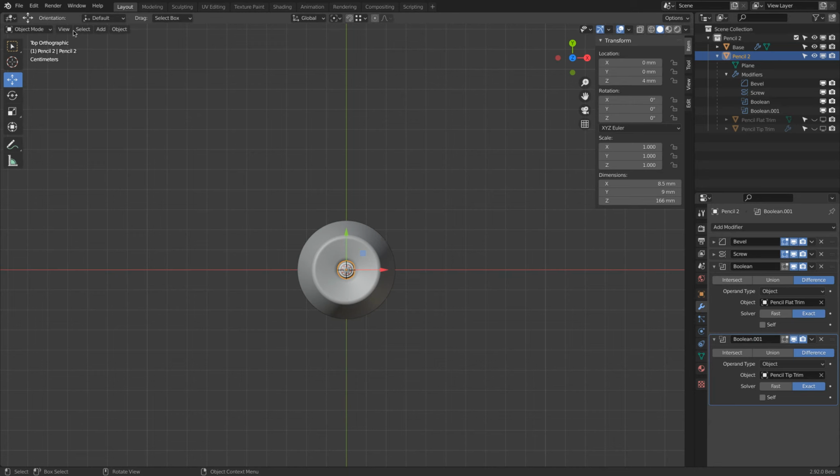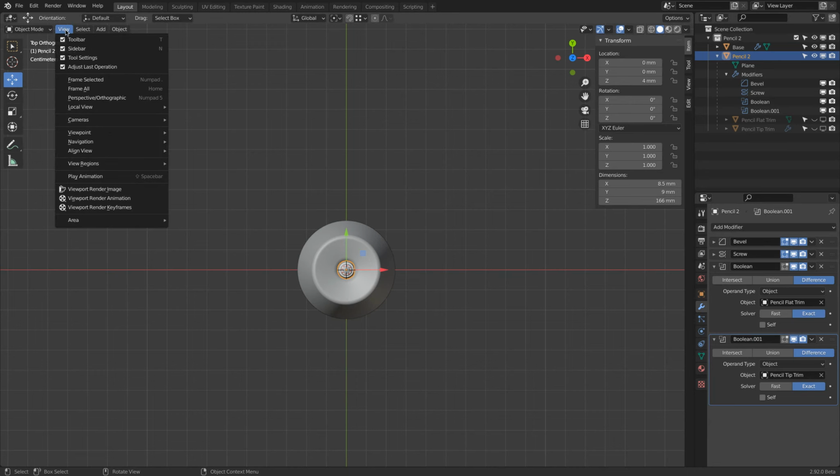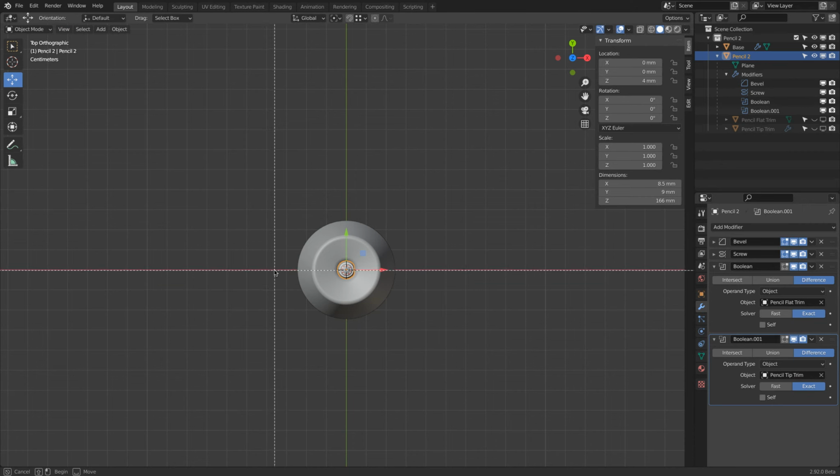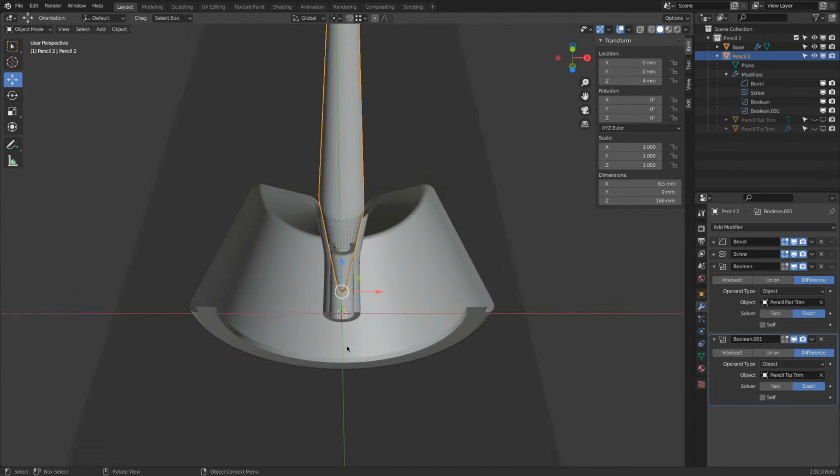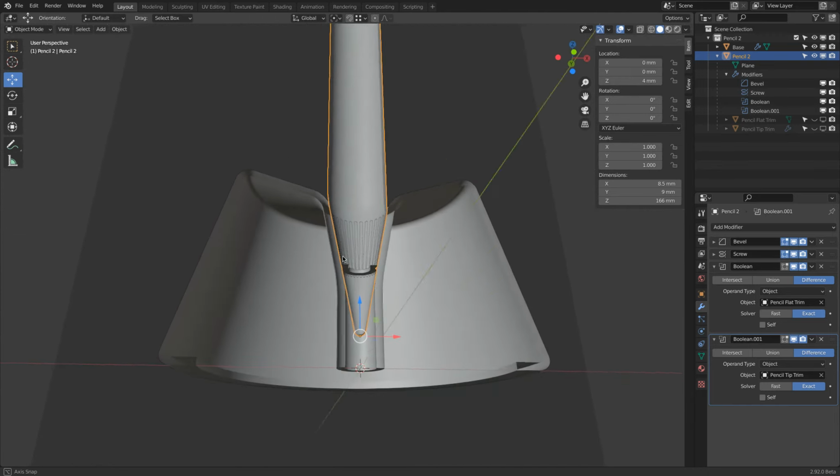One last interesting check. So with Alt B, and do we have view region? Yeah, here. So Alt B or Control B. I can draw a selection. When I release the mouse, then you see everything is clipped. It's kind of like a cut section view.